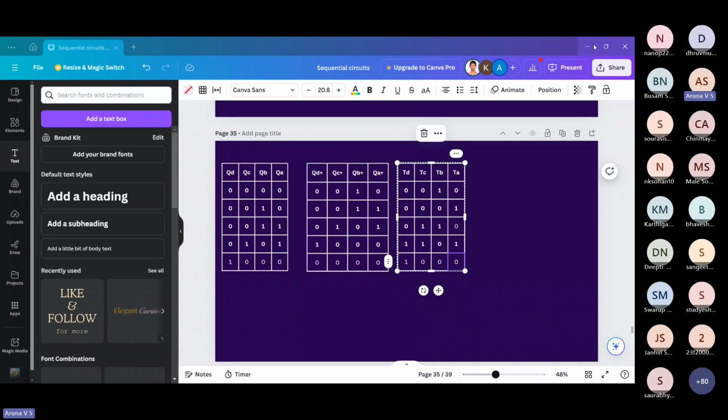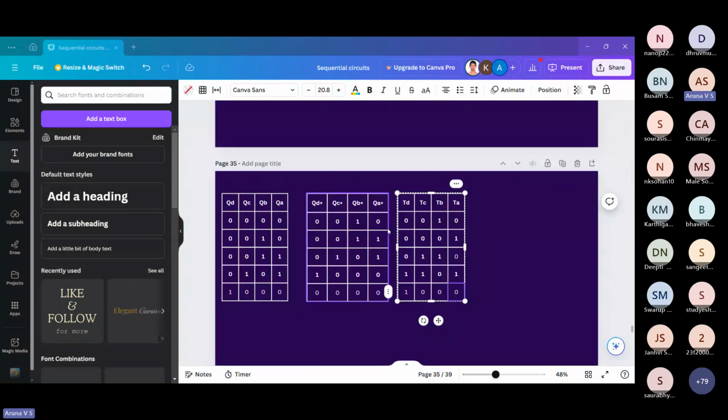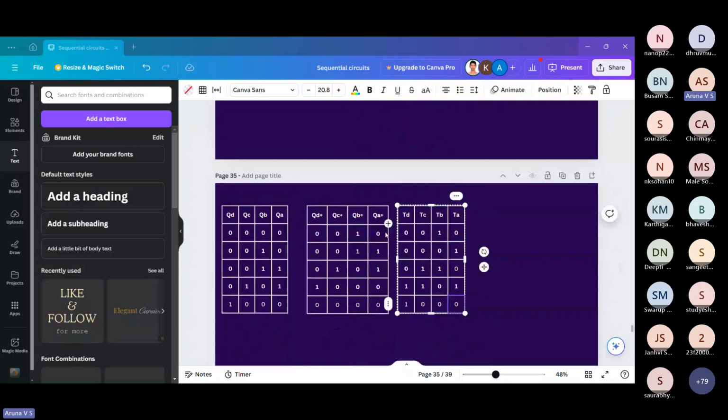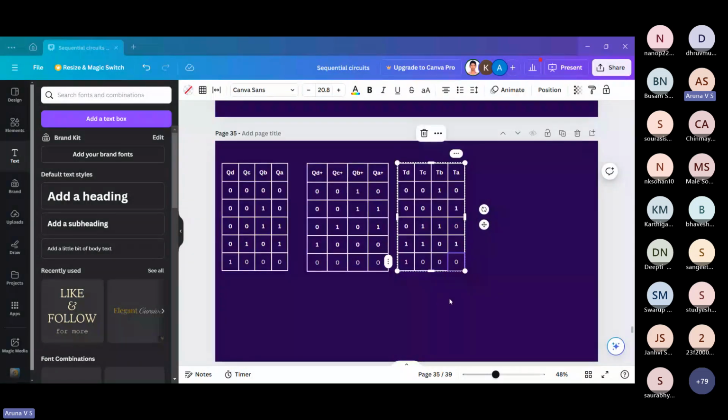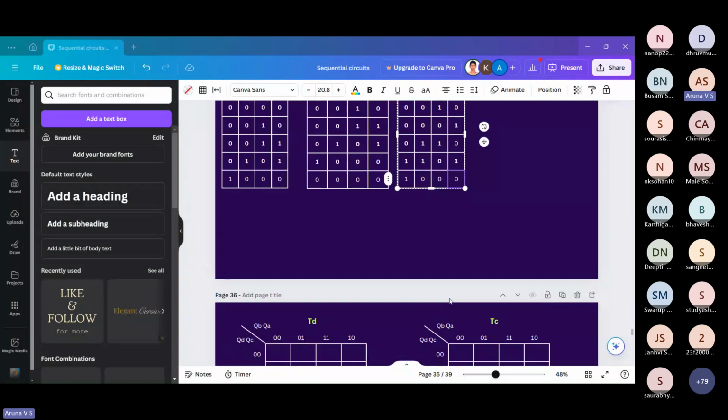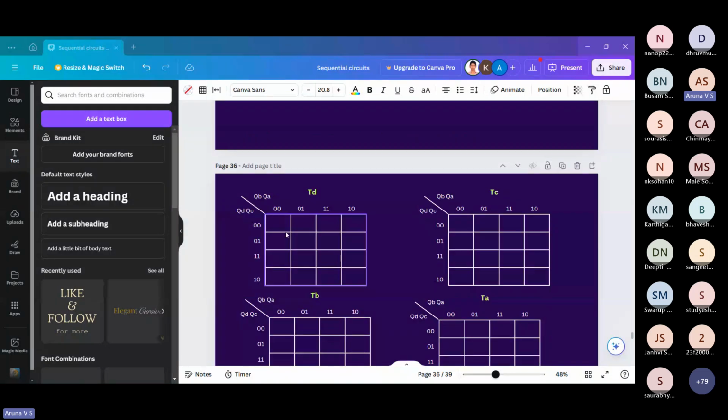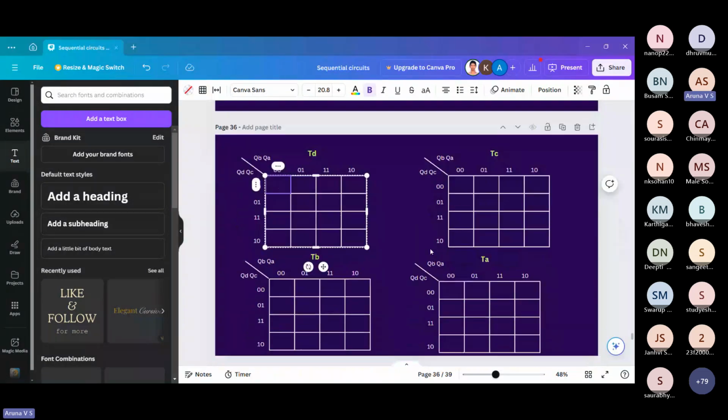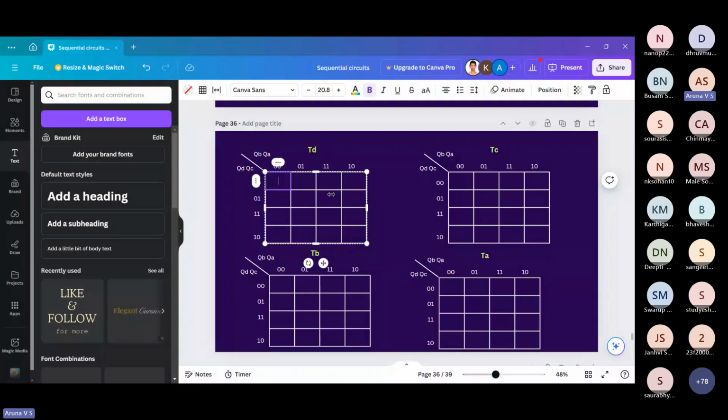So guys, if you see, we are leaving a few states, right? One we don't consider, and three, oh, I think three is there. So four we don't consider. Those are called don't care conditions. In K-maps, you can represent it. So I'll do one K-map, and you'll be able to do the others.